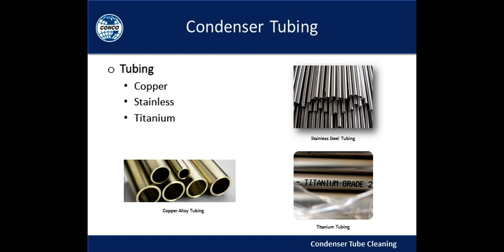Now, people argue that they have installed titanium tubes and they no longer need to clean. Well, that's simply not true. I will say that they will have a longer incubation period from the initial installation until their first cleaning, but after the initial cleaning, the fouling will occur at the same rate as it does on the stainless steel tubes. So please keep that in mind.